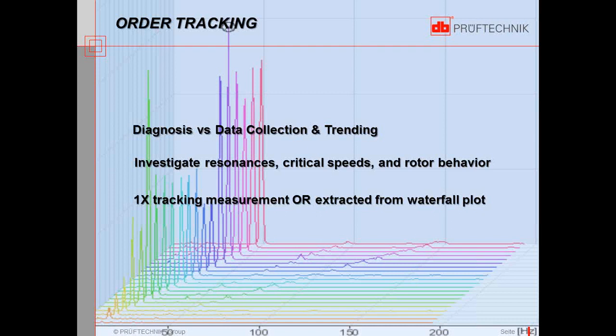Order tracking is most commonly used to investigate resonances, to investigate critical speeds, or generally speaking, what is the rotor doing as a function of RPM. There are a couple of different ways that we can process order tracking information, so we want to look at those and discuss them a little bit.